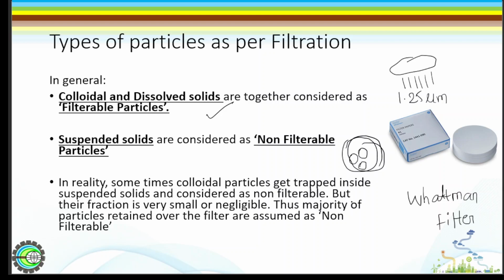The majority of the particles that are retained on the filter mostly come under the suspended solids. So we use the term suspended solids as equivalent to non-filterable, and the dissolved and colloidal solids are together called the filterable particles.